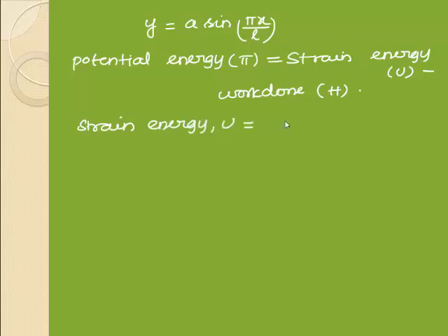U is equal to integral 0 to L, d square y by dx square the whole square into EI by 2 dx.